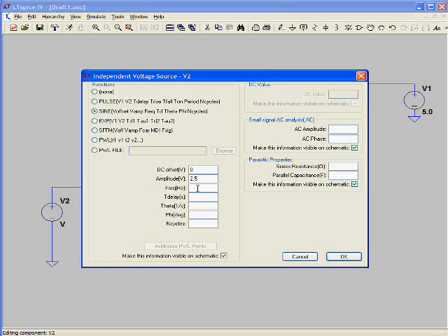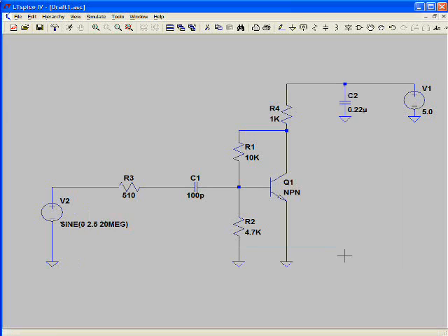Frequency, let's go mid-scale for this guy. Let's say 20 megahertz, and megahertz is kind of weird for this frequency. M, just a capital M, does not work. You have to do MEG. Kind of ugly, but that's just the way it is. And we can say OK there.